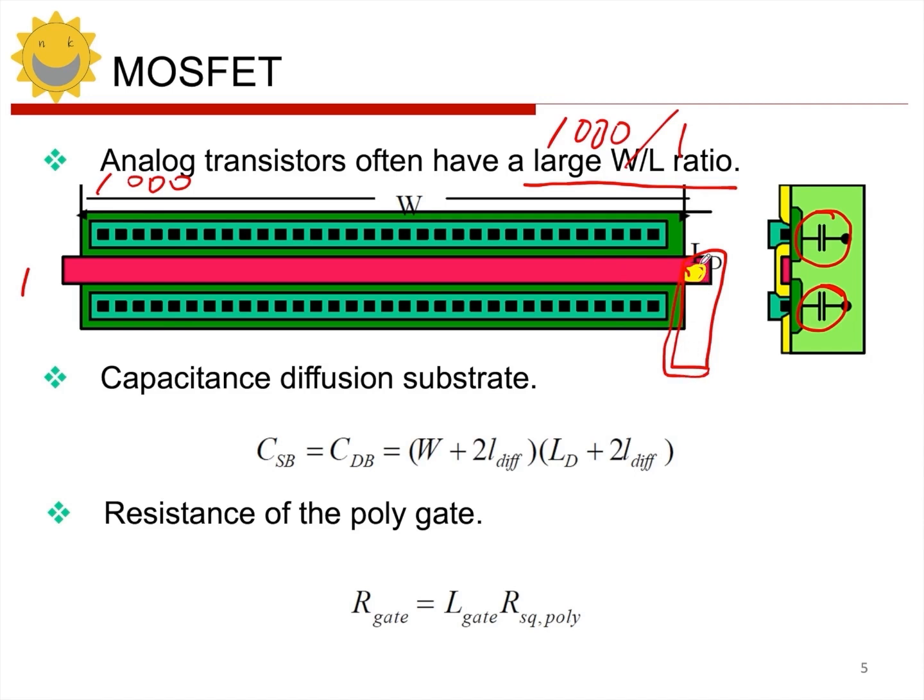So if I apply a signal to the gate here, when the signal is transmitted into the circuit, there will be an RC issue, right? Although the gate is indeed a capacitive load, it won't cause continuous current, but the gate has a large sheet resistance, and there is a capacitance between the gate and the substrate, right?